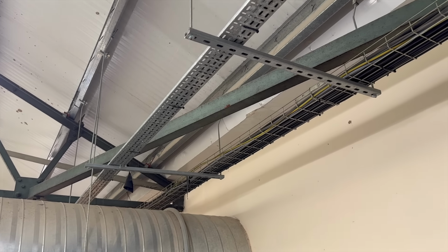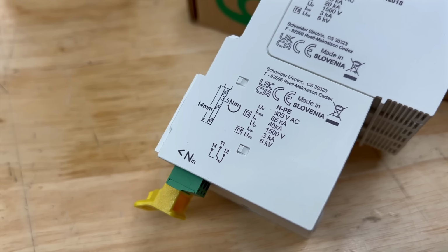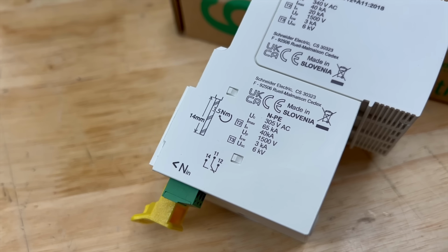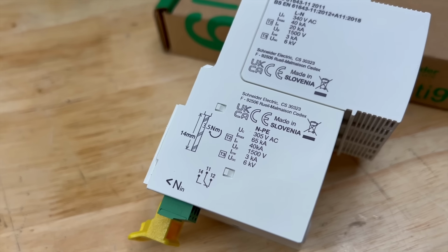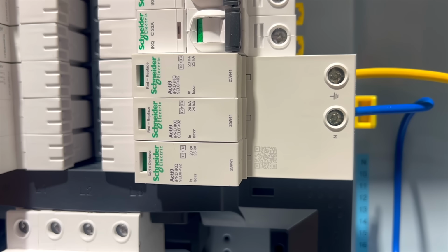So what type of SPD should you install when installing a subboard? If the equipment connected to that subboard is more than 10 metres from the upstream SPD and maintaining the declared voltage protection level at the load is important, then coordinated surge protection at that subboard should be considered in accordance with regulation 534. And does distance make a difference?